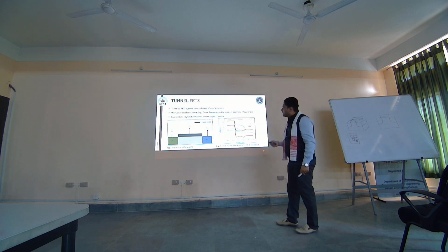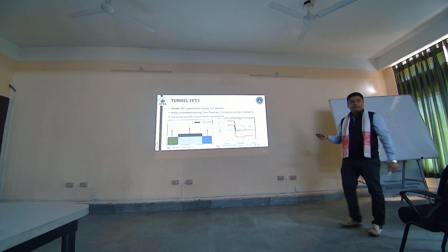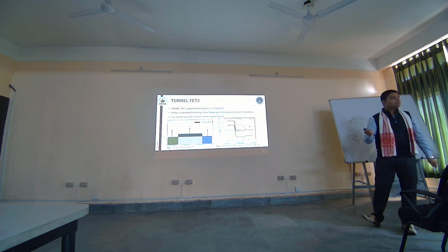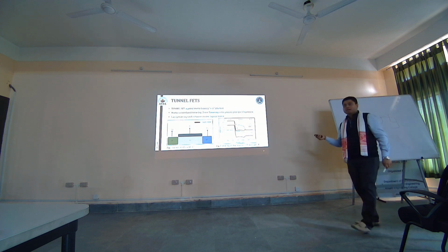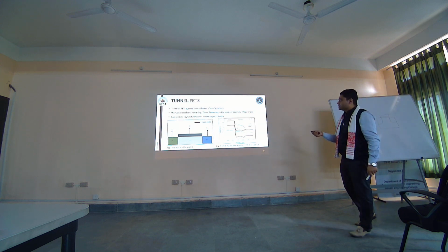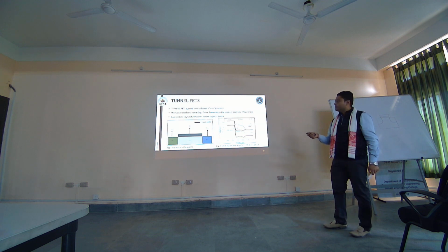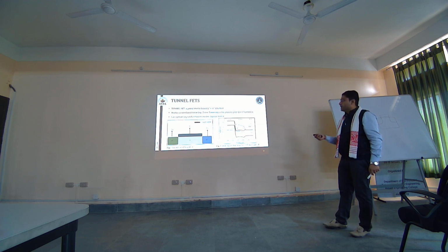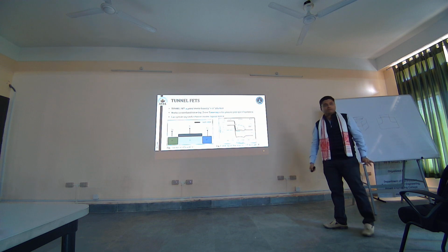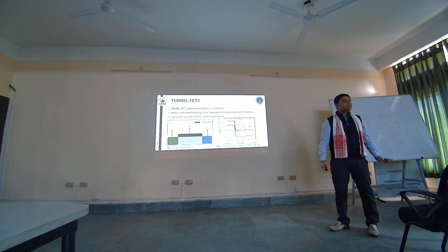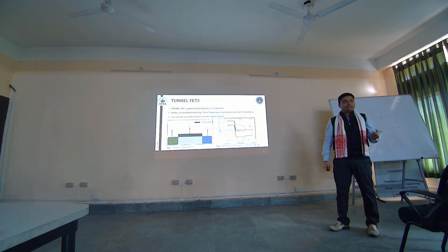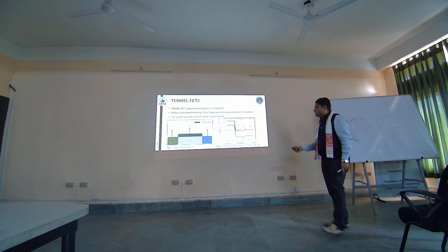So this works on interband tunneling, or Zener tunneling, which also happens in PN junctions, right? In very high doping and applied reverse bias, you can have this Zener tunneling, and it can operate in P and N channel mode, so it is an ambipolar device. But throughout our entire discussion, we will be focusing on only the N channel. Otherwise, it will be confusing.